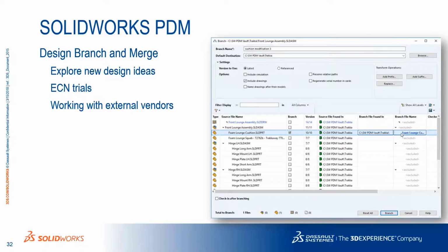This branch is a separate file that just doesn't have any of the references, but SOLIDWORKS remembers everything behind the scene. So you create those ECN trails and the auditable capabilities. And you can take that branch and do whatever you want with it. And if you like the result better than the original, you can then merge it back into the assembly simply by right-clicking on the part and saying merge. And SOLIDWORKS PDM, with all the behind-the-scenes connectivity, will just override the geometry. So it's very easy to do. I'm going to show it off in just a second.